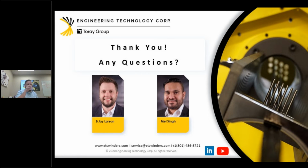All right, next question. Is there a limitation for the size and weight of a part to be wound? Considering long mandrels with big diameters, is it possible to use intermediate supporting structures to help the winding process without impairing the quality of the wound part? We do have customers that have supports. These customers are running products or parts that are about 50 feet in length. They're narrower parts, so they do have some whip. In the middle, they sag while they're winding it, and they do have a rest that comes up. It has very broad rollers, and it does support the part.